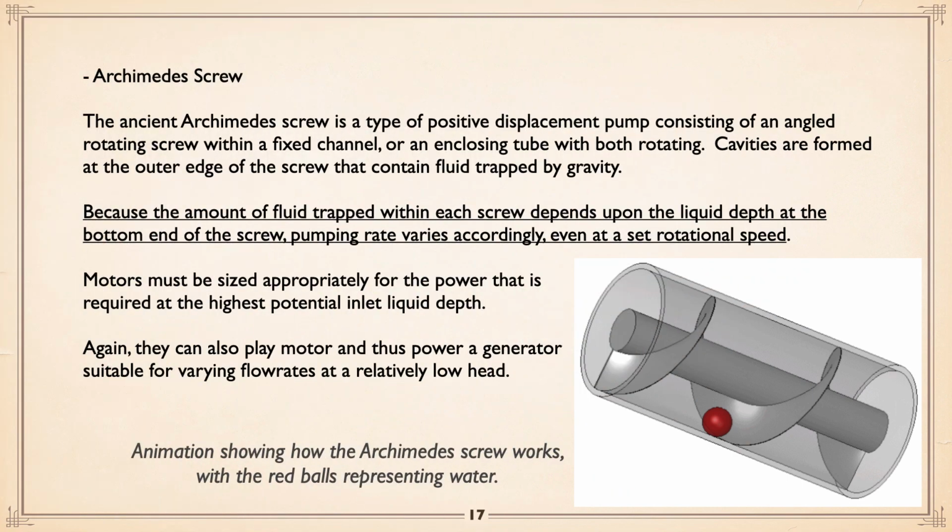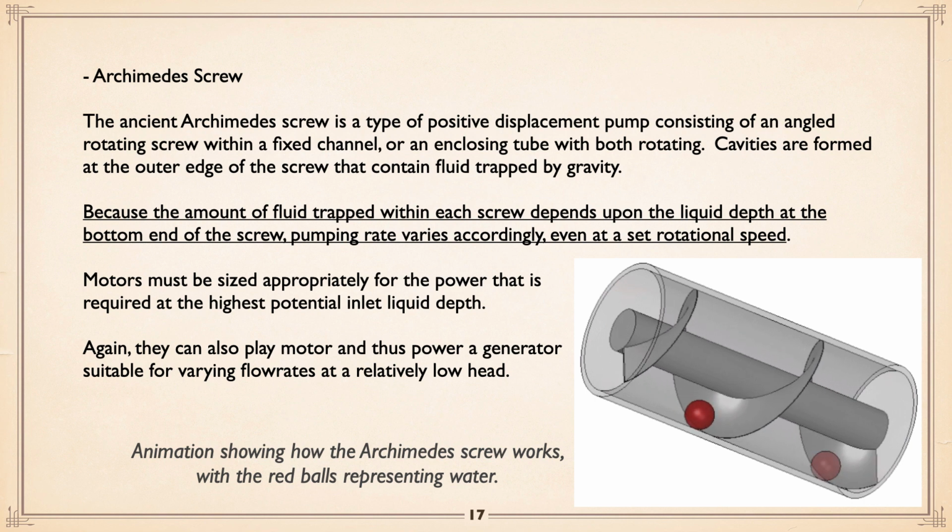Now, something that is seen in municipal more and more nowadays is the Archimedes screw, which goes back a long time. As you can see, chambers are formed along the bottom, and as the screw rotates, the fluid will pump up. Very often, in fact most cases, the thing is only half or less full of water as it moves its way up.